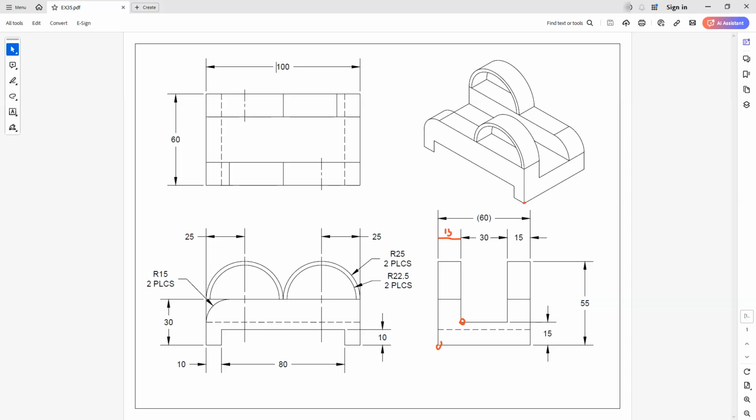Okay, and I will apologize for my handwriting here with the mouse. All right, so my first number is 15 comma, and how many units going up? Well, it tells me right here that it is 15 going up. So I'm going to start off with the rectangle command, and I'm going to type in 15 comma 15. That's going to put me at this point. Now I need to tell it where to go from here, right? So I need to get up to this point.